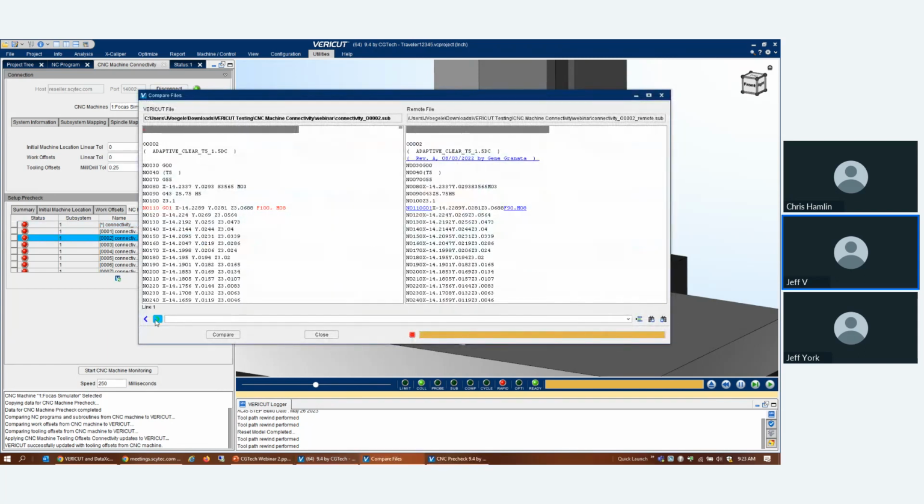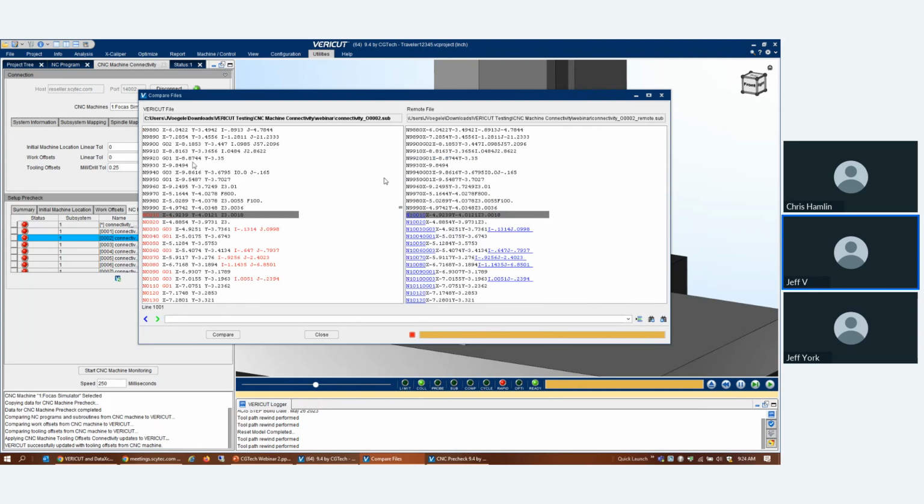You can see here, it also appears on one of these first lines that someone has gone in and maybe manually modified the feed rate. It looks like it went from 100 down to 90. So I maybe need to have a conversation with my shop floor and find out if there's an issue with the program that I do need to slow things down, or if there's some other kind of an issue. And it looks like I've got a couple other issues further down here. It looks like there was an issue with the end block number with the control reading that. So I had made a change. So I need to get my programs updated as well.